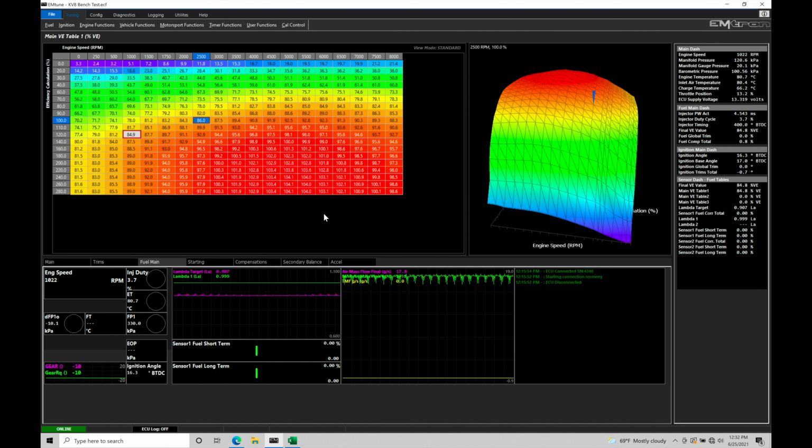That might be a low side or a high side output control. It also may be a basic on-off or a pulse width modulated type of output control. So it's important we understand these key differences and break those down, so that when we're programming, we know exactly how to program a particular device or circuit so we get the exact results that we're after.